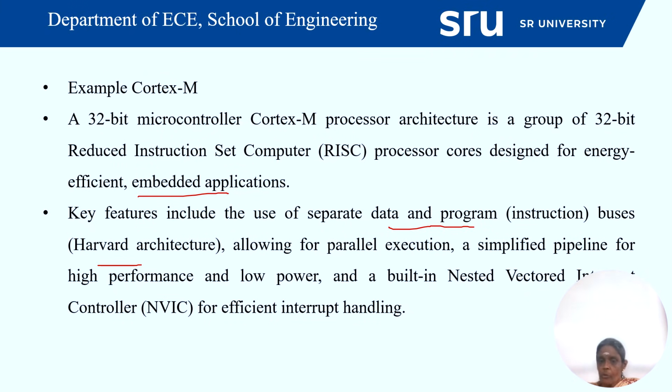Normally in microcontrollers, 8051 microcontroller or 8085 microprocessor, we do have address and data multiplexing. So the buses will not be separate for code and data. So address and data will be multiplexed in the buses.